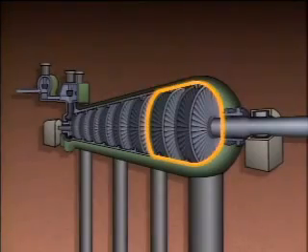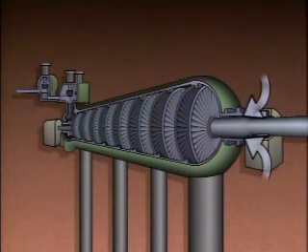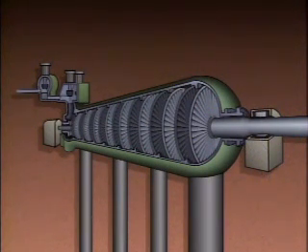In the turbine stages in which pressure is less than atmospheric pressure, air will try to leak into the turbine. This reduces turbine efficiency because the air must be removed in order to maintain the vacuum. Air leaking in also can cause a thermal stress problem in the turbine. The outside air can be much cooler than the inside of the turbine. And when cool air gets into the turbine, drastic temperature changes occur. The resulting thermal stress on turbine parts could cause them to crack.